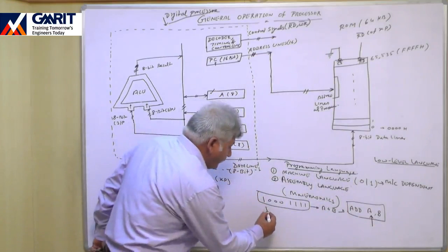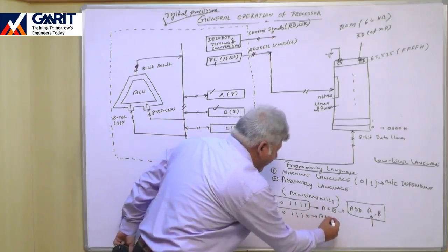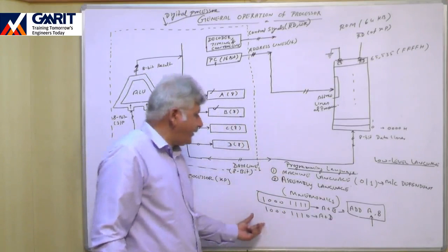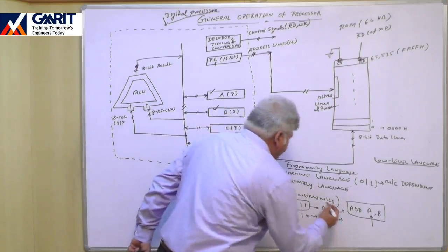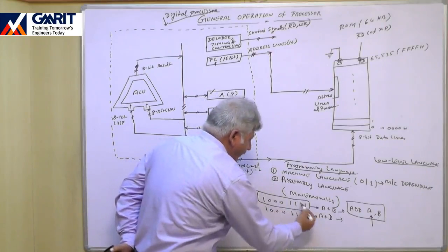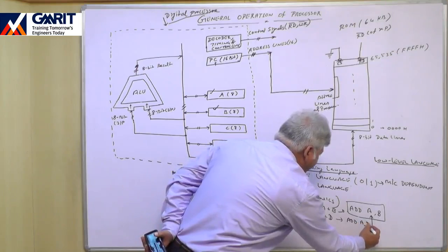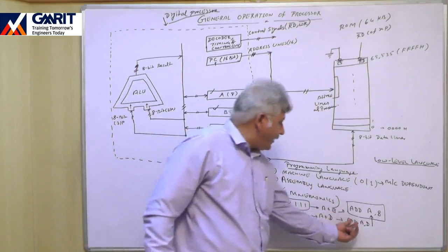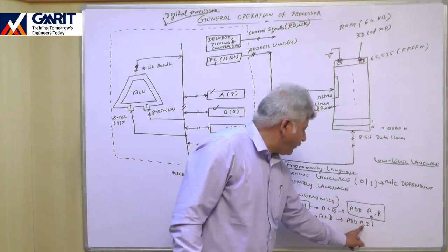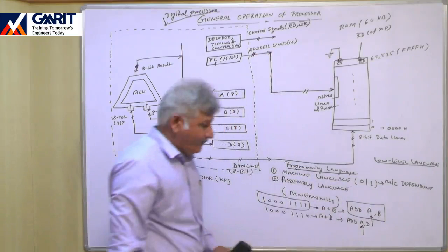Now another binary pattern, 1 0 0 0 1 1 1 0. Suppose this is used to add A and D. This binary pattern is used to add A and D. So the designer of this processor has given one mnemonic for this particular binary pattern, and that is add A, D. So when we write add A, D, then the processor will perform the operation of addition of A with D, and the final result will be stored in A. Right?